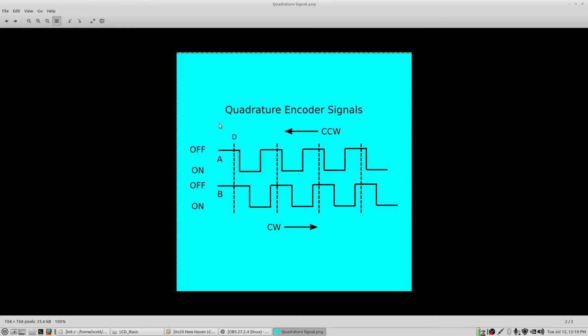When I started this project, I went with one interrupt service routine set for INT0 and INT1, which counted each detent as one. It worked out okay, but since then I've discovered there's a better method to deal with this encoder as an input device, and it triggers on all four of these events. So you've got a level change here, which is 1, a level change here, which is 2, a level change here, which is 3, and a level change here, which is 4. So there are actually 4 level change events between detents. This most recent interrupt service routine counts 1 count per each level change event. It's a little bit better, and a little bit less sensitive to mechanical issues and other things that I found creep into these Bourns rotary encoders. So that's what's going on with that.